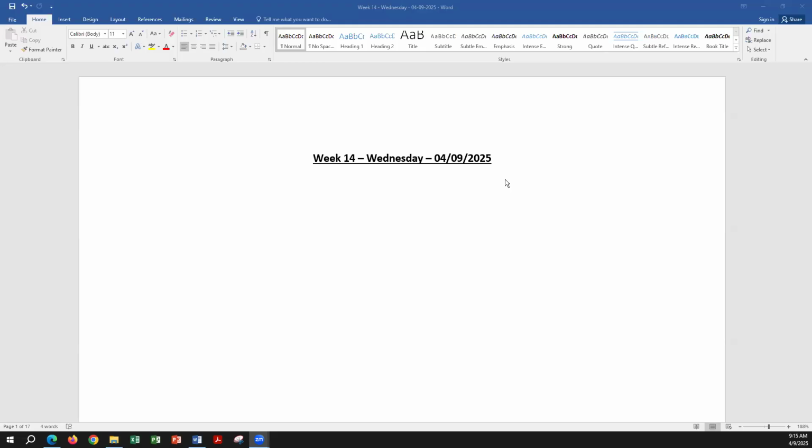Because the reactance of the capacitor, 1 over j omega C, and the reactance of an inductor, j omega L, are also dependent on the frequency. So if omega is changing, then the reactance of those components are changing, and your response is going to change at the output, whether that response is current, voltage, power dissipated, or whatever it is. So that's what we are going to look at.